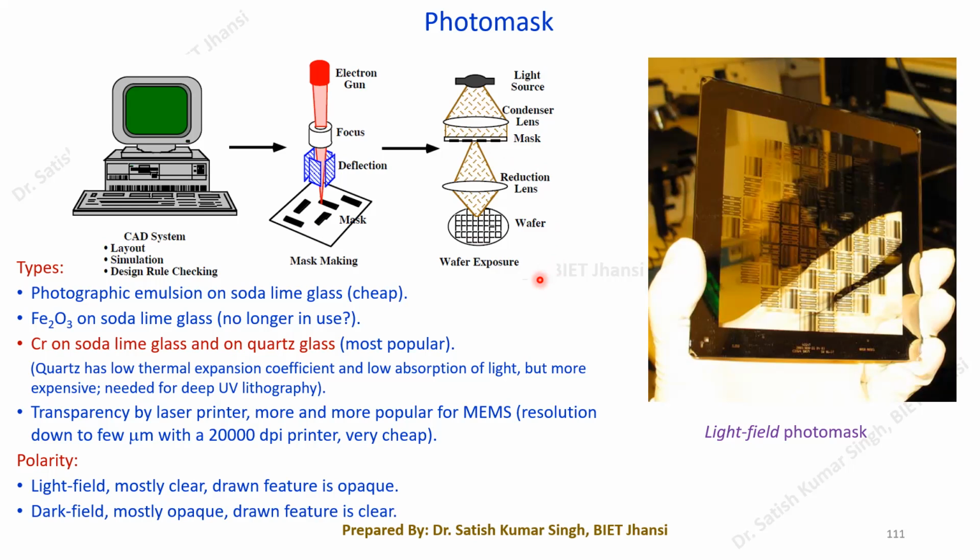By whatever way we have fabricated it, if we keep this photo mask in this region and then expose the wafer, there is a chance, because this type of system must be kept in a certain environment. If the environment contains dust particles, then a dust particle may sit on your mask also.